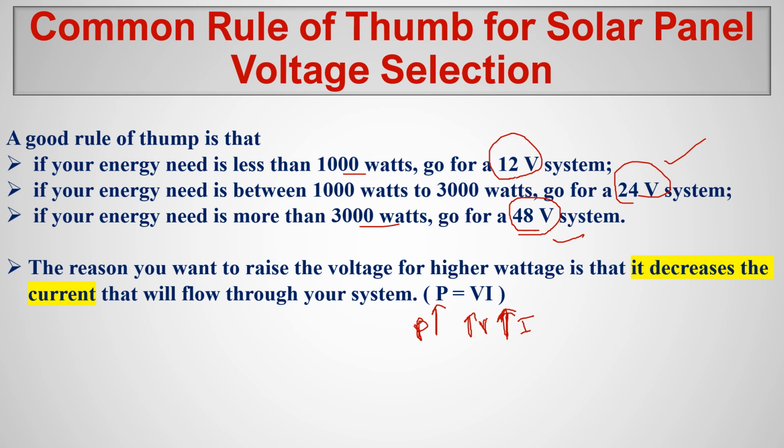If the cable size becomes large, the installation cost is high, the material cost is high, the total project cost is high. So the idea here is, in electricity, we always try to keep the current at a minimum, low value. We are okay with increasing the voltage, but we don't want the current to be increased. Okay, that is the idea here.